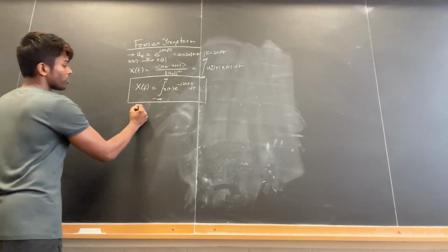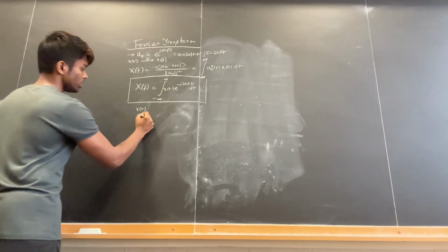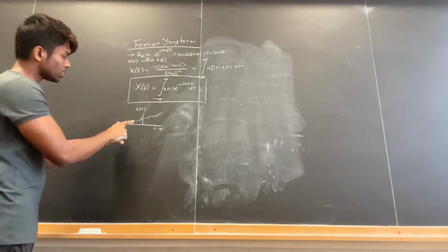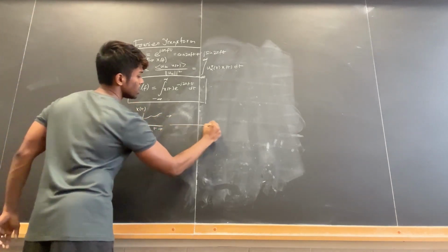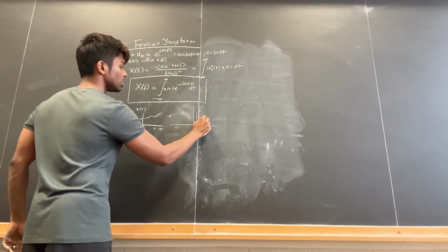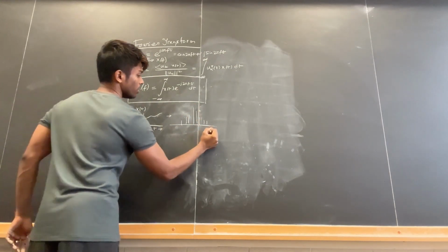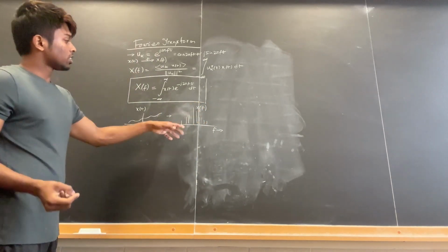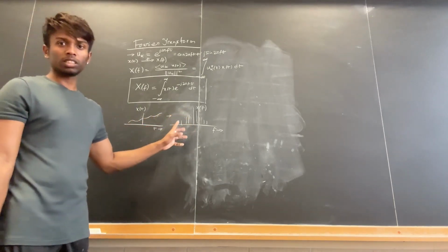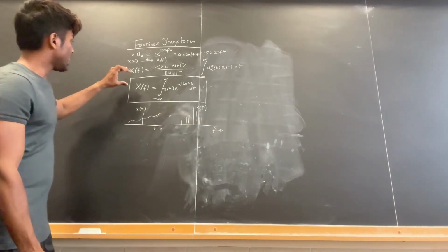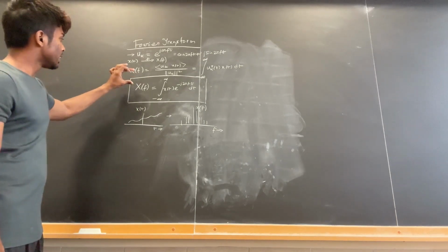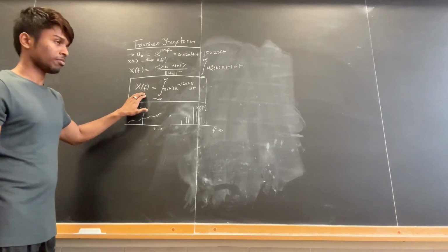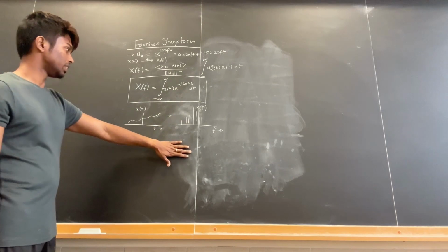A Fourier transform transforms the signal in the time domain. So there is a time domain representation of the signal, something like this. xt varies over time. And this time domain signal is transformed into a frequency domain signal with a certain discrete variation in the frequency domain, where it varies over the frequency, and that is xf. So this is a discretization from the time domain to the frequency domain with certain frequency spectrum. So what xf gives us, the Fourier transform gives us the oscillatory behavior of the signal over the frequency f that is contained in the signal in the frequency domain.